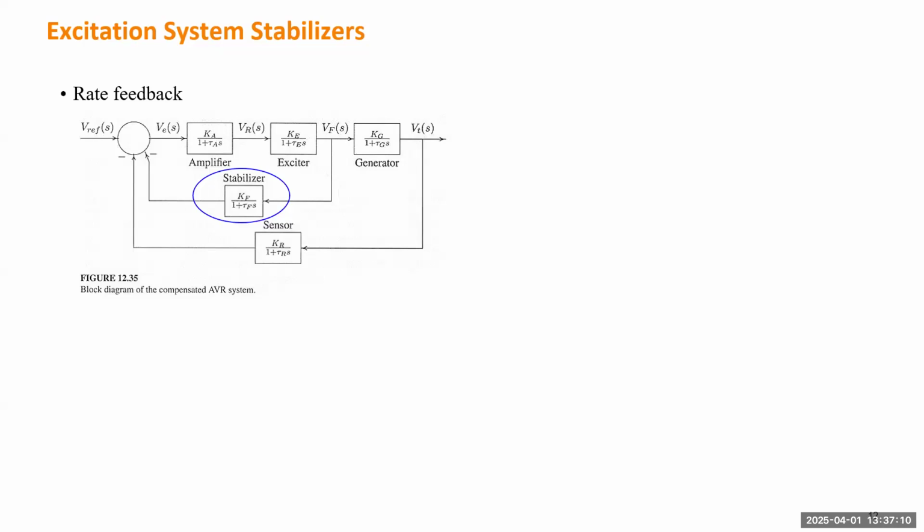The simplest idea is to just add another feedback loop. This will be part of the excitation system. Those elements will be part of an excitation system. You simply add this feedback loop. Okay, so here you need to design the gain, KF, and the tau F. Tau F may be something you cannot design, depending on what technology you use to implement the control, but you can design it. Definitely, you want to make tau F proper for your excitation system, and you can design the KF.